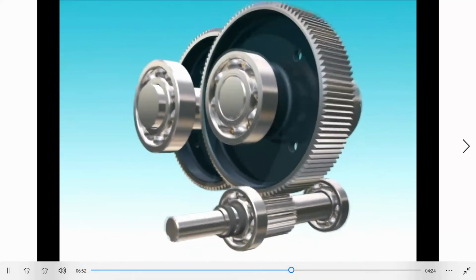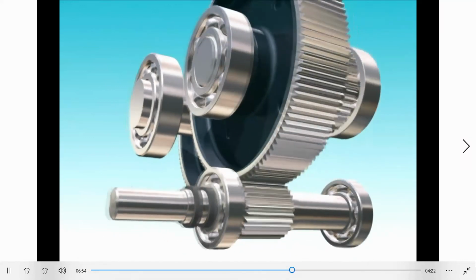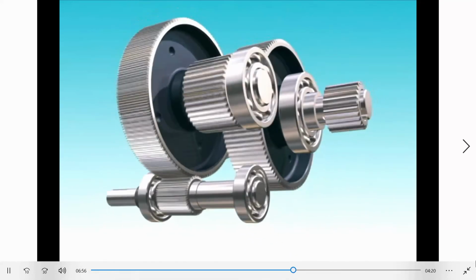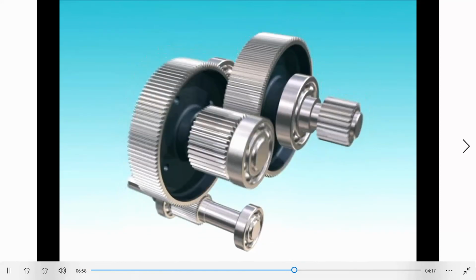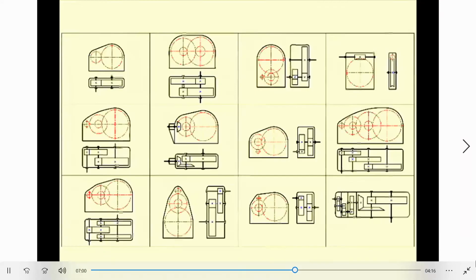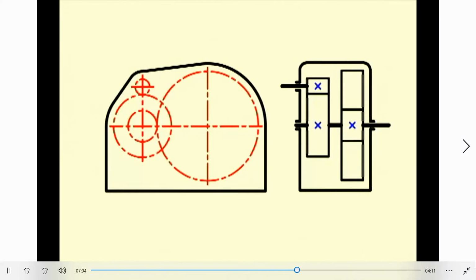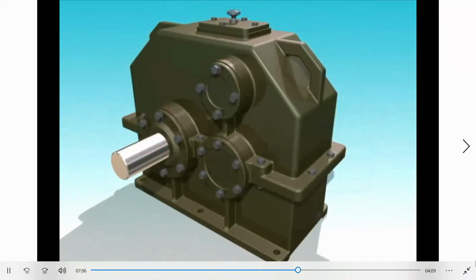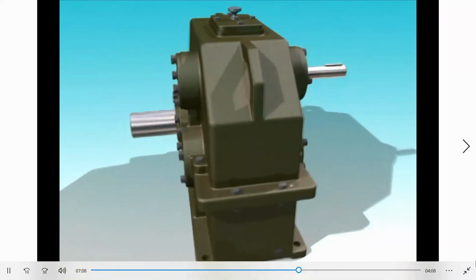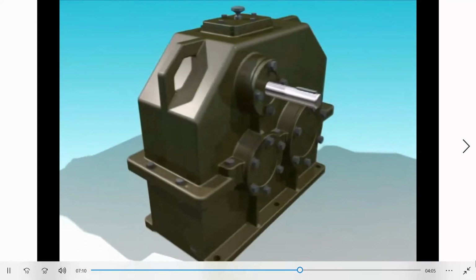In this gearbox, the high-speed stage is vertical and the low-speed stage is horizontal. Such a type of construction can make the gearbox more compact. This is another variant of the L-shaped gearbox. In this case, the drive shaft is located overhead rather than below.